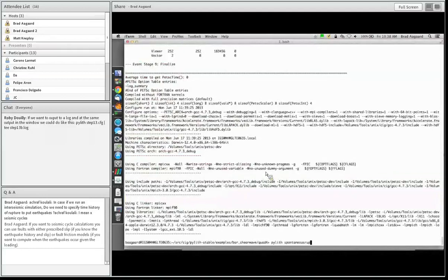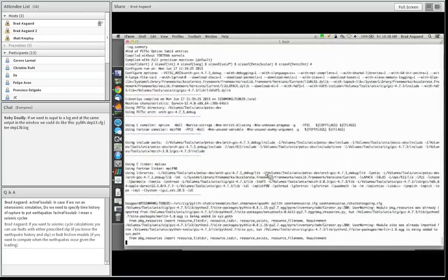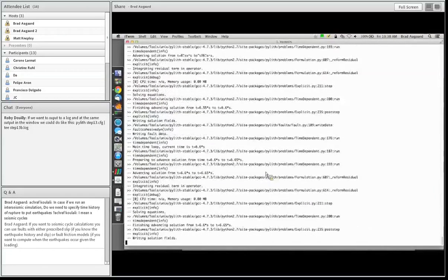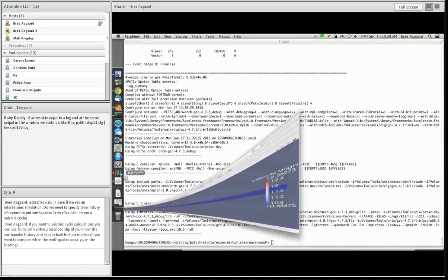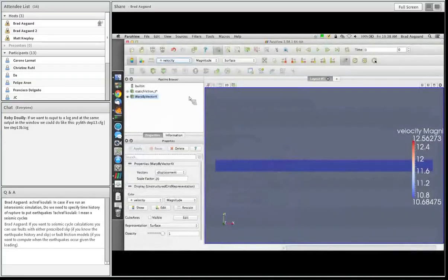And I should highlight again that with Pilot 1.9, we've greatly improved the robustness of explicit time-step and rate and state friction. We are now confident that we have a stable solver implementation of that with a Newton-Raphson in log slip space to get the consistent coefficient of friction for a given slip rate. And so we've run some benchmarking cases with the SCEC dynamic rupture benchmark to verify that. We compare very well with other codes. Before, we essentially just had a robust implementation for the quasi-static case.